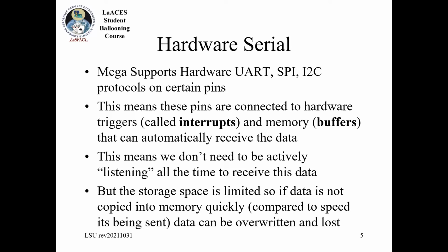And what this means is your program can be doing other things. You can be doing calculations, you can be doing communications on other pins, but because the hardware level in the microcontroller can handle this little bit of data on its own without you checking on it, you don't have to actively be watching the port to get the data.